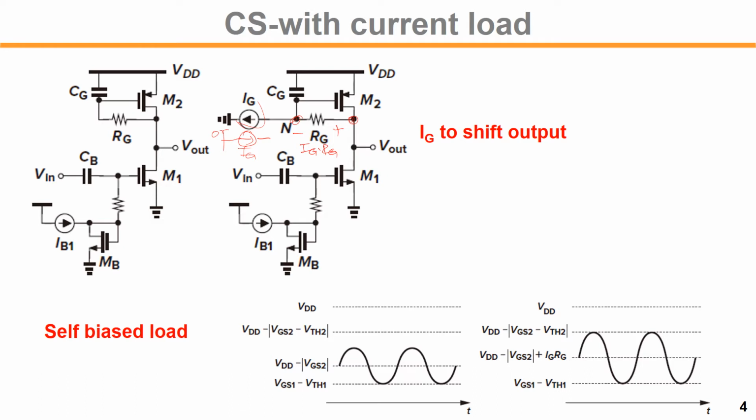So in this example, the typical previous case, the output common mode is VDD minus VSG2, right? So the output can go down by this level, which is overdrive of 1. The lowest peak is from here to overdrive, but it can go up by the same amount. In this case, the maximum output peak voltage would be VDD minus overdrive 2, right? VDD minus overdrive 2.